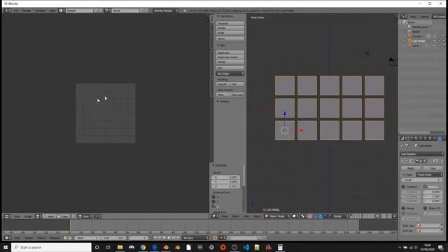This one here, because it's a square, is a ratio of 1:1. And UVs are relative to the overall texture size that we set. So something that is positioned halfway across the UV map will always be halfway across the UV map, whether we change that resolution to 512 by 512 or 4096 by 4096. It will always hold its relative position, which is quite a nice handy thing.